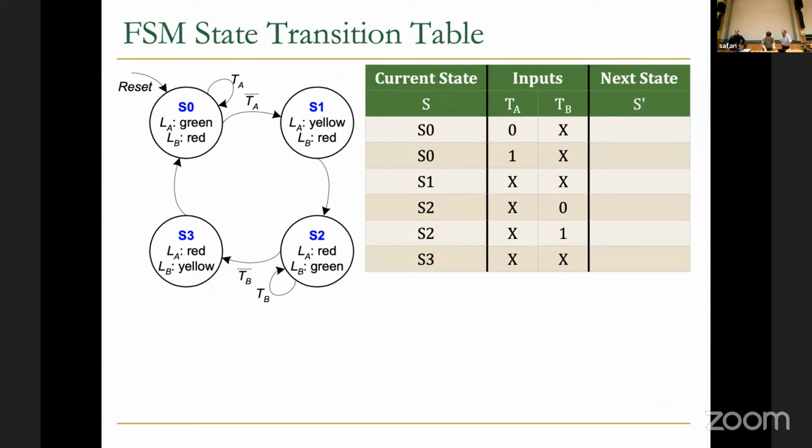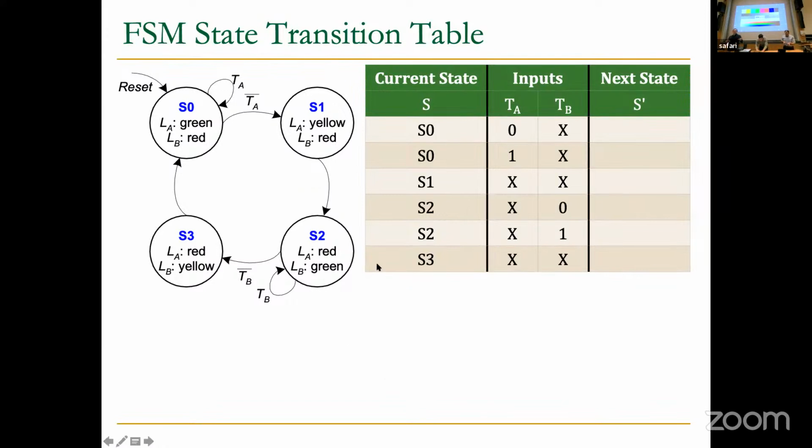Any questions? What we're going to do is basically build essentially the output logic, next state logic, as well as the state register. Any questions so far? Yes, please. Are there other types of finite state machines, other than Moore and Mealy? There are other classifications like synchronous versus asynchronous, like we discussed last time. The sequential lock finite state machine was an asynchronous finite state machine. So certainly, yes, there are other types of finite state machines. But in terms of how outputs are generated, based on dependence on the state versus state and inputs, it's just Moore and Mealy.